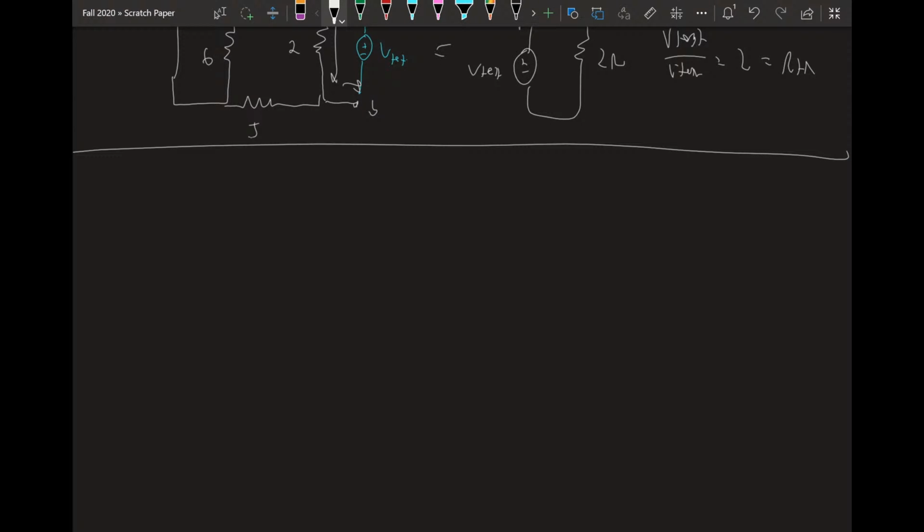Let's talk about capacitors and inductors. So, what is a capacitor? A capacitor is a circuit element that stores charge between its parallel plates, if you want to get into physics, right? Has some voltage across it, has some current through it. The voltage-current relationship is given by the current equals its capacitance times the time derivative of the voltage. And then solving this, you can find that the voltage as a function of time equals 1 over C times the integral of the current